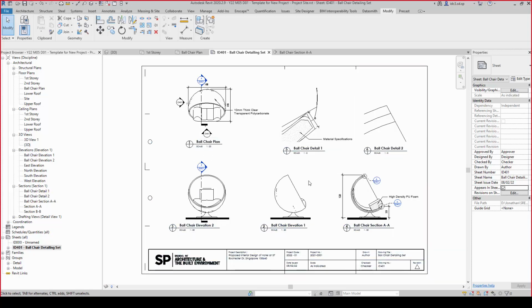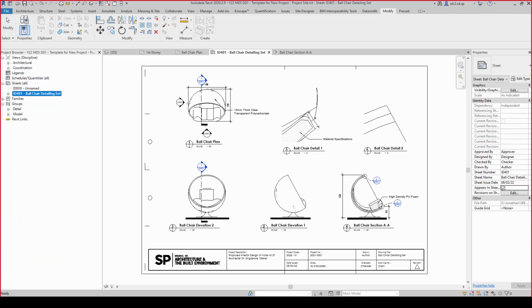Okay, but then this one is embedded inside your project. Remember, your whole project. So you're going to see a lot of drawing sheets down here already for this part here on detailing. So that's why I run a demonstration to just show you how to take in an RFA file to import into the project, and then how to isolate it so that it becomes a detailing set.